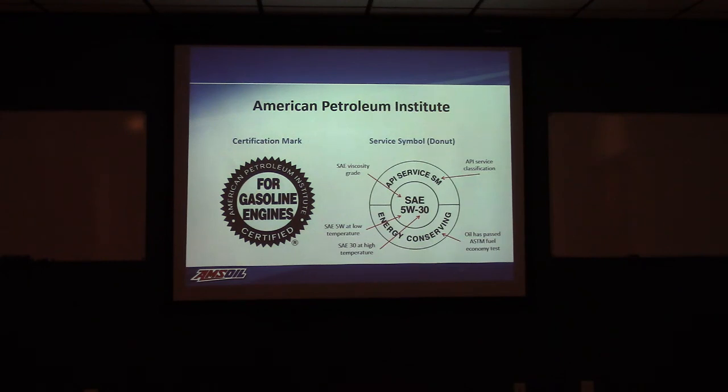Down on the bottom, we have energy conserving. A lot of that has to do with what we refer to as ILSAC, which is very, very concerned about providing additional fuel economy. If it's energy conserving, it suggests that this particular oil will provide you a little better economy than oils that don't meet that requirement. And when we're talking a little bit, we're talking a real little bit. Don't expect 5-10% or anything like that. We're looking at 2% or less. So nothing huge, but it's there.